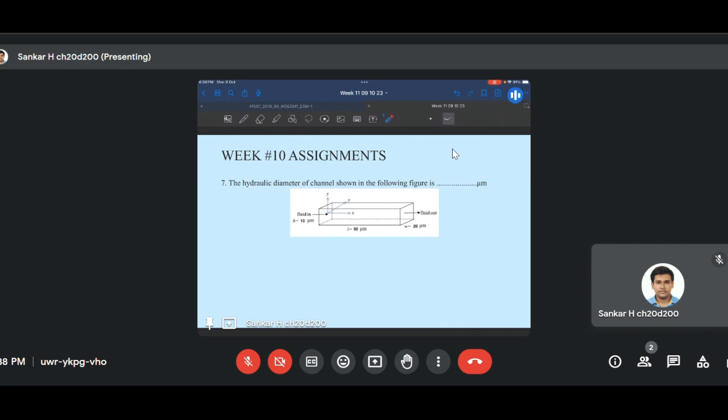Similarly, since it is a wetting phenomenon, fluid is wetted on these two faces and the faces opposite to each of these two faces. So there will be four faces, and the perimeter of that has to be considered, the perimeter in the flow direction.